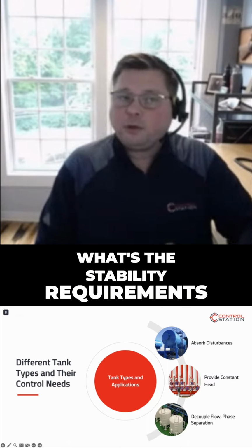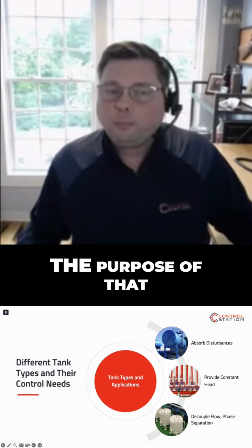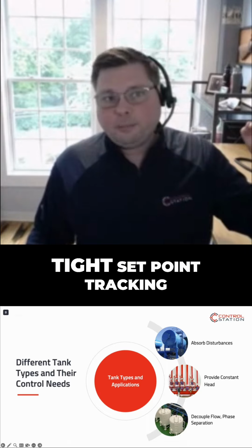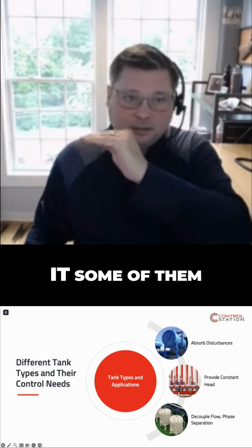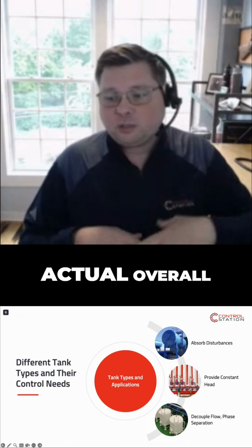What's the safety considerations? What's the stability requirements? What are the efficiency requirements? And so you have to think through what the purpose of that level controller is. It's not always super tight set point tracking. In general, some of them can be that way, some can actually be counterproductive to the actual overall control